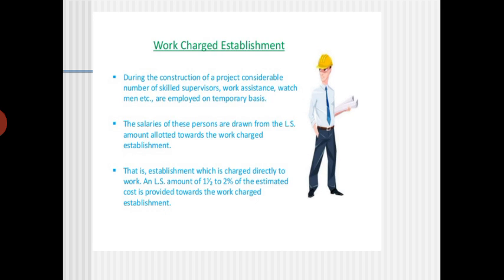Then work charge establishment. During the construction of the project, a considerable number of skilled supervisors, work assistants, watchmen are employed on a temporary basis. So the salary of these persons is to be drawn from the LS amount allotted towards the work charged establishment.